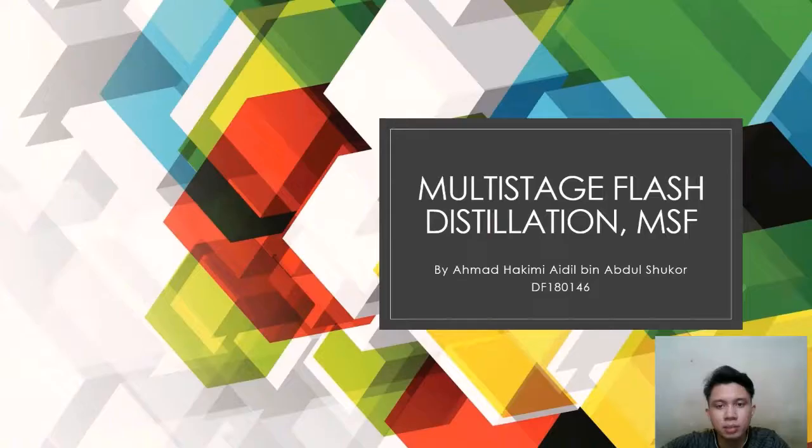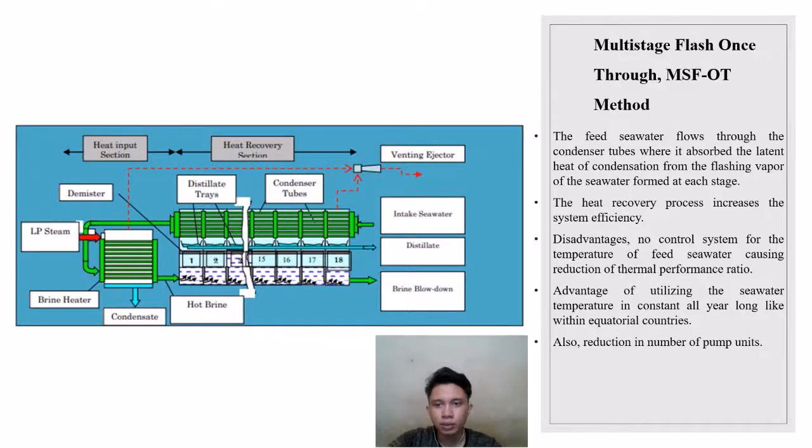Multi-stage flash distillation, MSF-OT. The disadvantage is there is no control system for the temperature of the water, causing a reduction of thermal performance ratio. The advantage is utilizing the seawater temperature, which is constant all year long, like in equatorial countries. Also there is a reduction in the number of pumps.